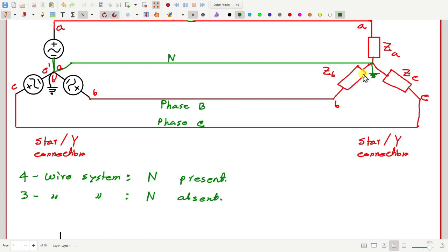One problem, if you do not ground anything, then the absolute values of the voltages are undefined. All voltages will be floating. Then we can only define the relative voltages between two points, but absolute voltage is undefined. But when you connect any particular point to the ground, then that point is at zero potential with respect to ground, and all other points in the circuit will have precisely defined absolute potentials.